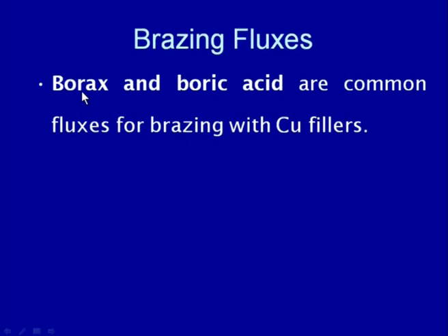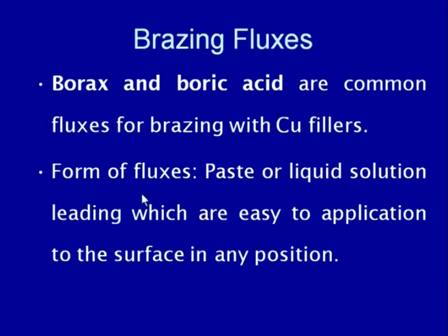The fluxes which are commonly used for performing their role, meaning reacting with the impurities and removing them in the form of slag, are borax and boric acid. Borax flux or boric acid are commonly used for brazing with the copper filler metals, and these fluxes can be used in the form of paste or liquid solution, which can be easily applied at any position during the joining process.